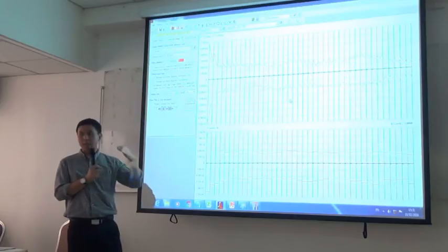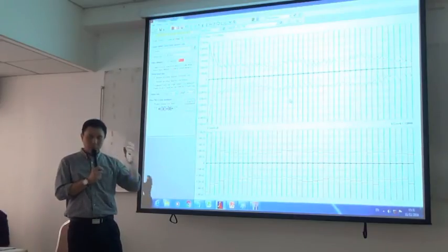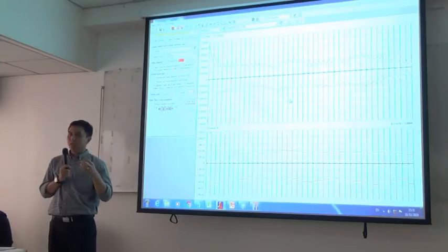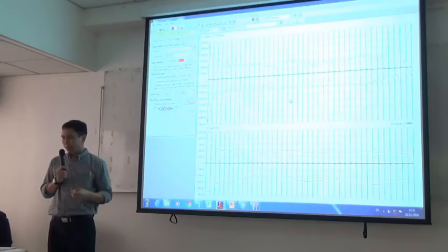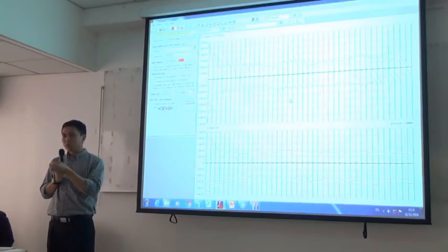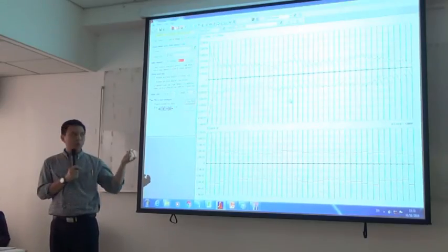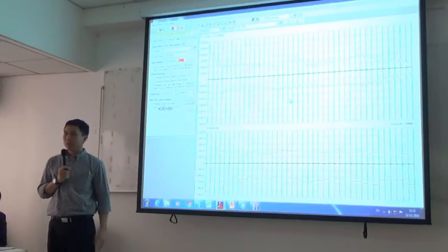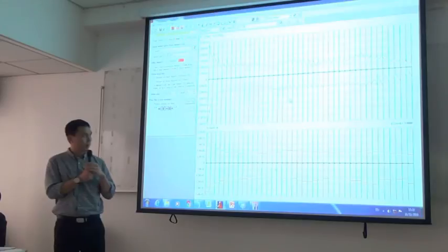So we should check step by step, and if the column moment is increasing due to the yielding of the girder, one thing we can do is increase the longitudinal reinforcement in the girder to prevent high yielding, so the column moment will not be increased significantly.